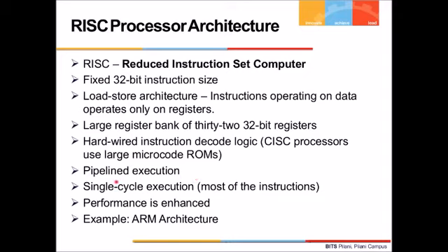There is single cycle instruction execution. The RISC processor is designed in such a way that all instructions complete in a single cycle. There are a few exceptions, particularly multiply kind of instructions, which probably cannot, but generally in the current RISC architecture they do.